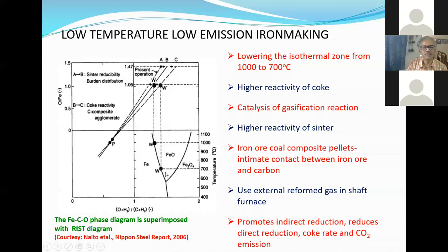And this is the FeO phase stability diagram. In the isothermal zone, at a particular temperature, this line is the Fe-FeO equilibrium line. At a particular temperature, you can see what equilibrium gas composition is required for that equilibrium. Most of you know this. This axis is O/C, and with hydrogen too if hydrogen is there; otherwise, for the Fe-C-O phase diagram, you consider O/C.